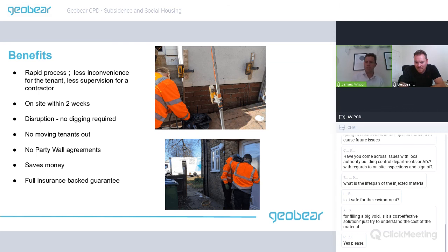Going back to, I think it was Richard's point of where it doesn't work. So yeah, if it's like a 20-story block of flats, don't come to us. We can't give you a solution for that. But up to 5 floors we can, and that covers the vast majority of residential properties. Yeah, and the materials we do use for ground strengthening as well. For example, there's York Hospital who wanted to put an extra story on an existing part of their hospital, and we strengthened the ground beneath the pads just so they could do that. So it's a really strong material.